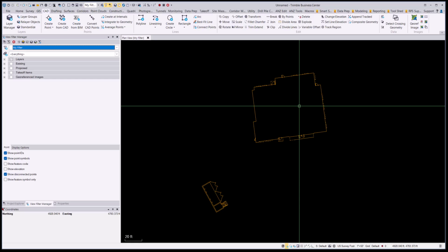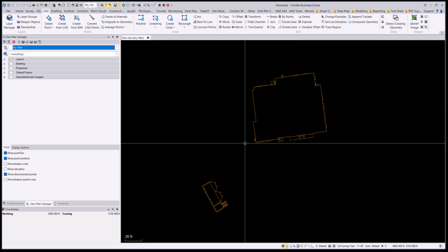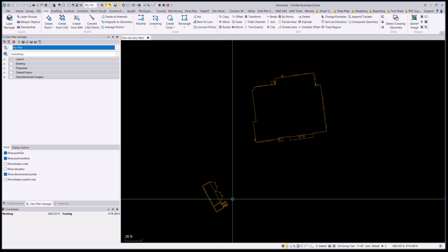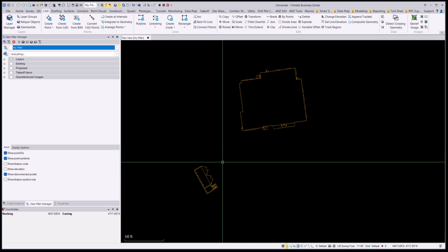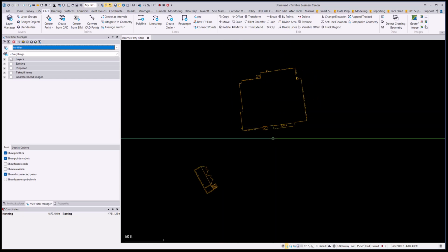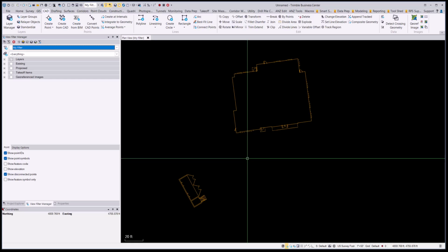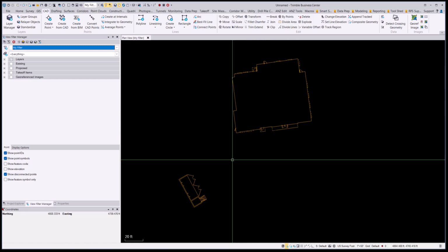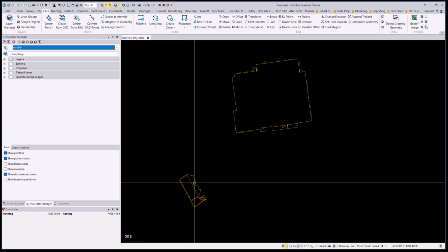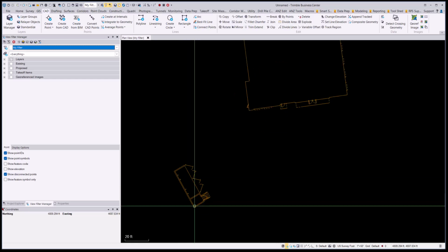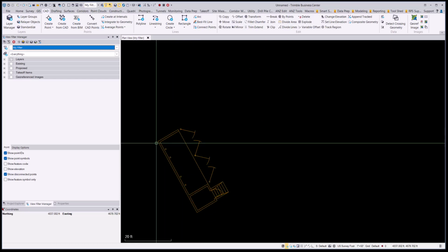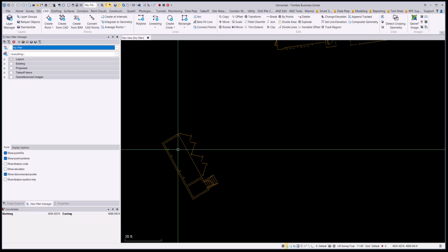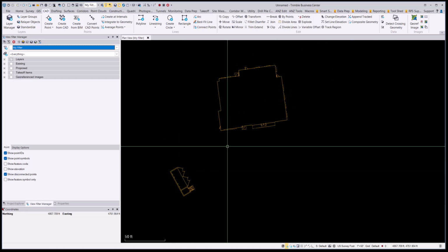Now that's actually good. So that pulled out our building line, and that pulled out our dumpster pad area. So I don't want all these doors and stuff because what I want is just a delineated edge so I can put my finished floor elevation in. I don't know if this has special elevation yet, but I do want to delineate it for a different type because the dumpster pad has a different subgrade thickness.